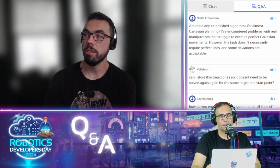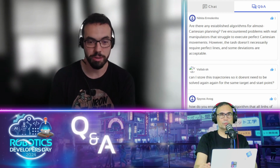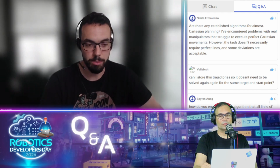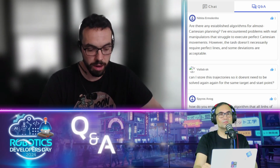Yeah, there are lots of options. At the end of the day, the big reason Cartesian planning fails is that you don't need your inverse kinematics to meet the Cartesian trajectory exactly at every point, like you said. There are some algorithms that let you parameterize this easily. One that I keep hearing about lately is called relaxed IK, which, as its name suggests, lets you relax certain constraints.